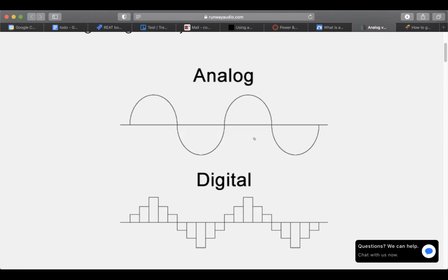However, the digital pins can only read, this isn't a very good visualization of it, but it can read the 0 value, or it could read the full 5 volts. Anything in between, it's not going to be too sure about. If it's 4.7 volts, it might say that's close to 5, and so it's going to accept it as the pin turned on. Or maybe it's only 1 volt, and it might interpret that as no, that pin is probably off. So digital, it's either on or it's off.